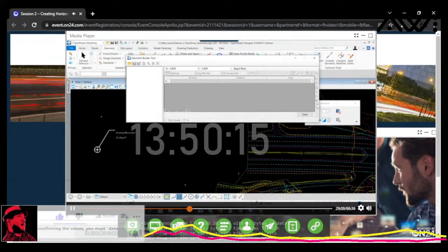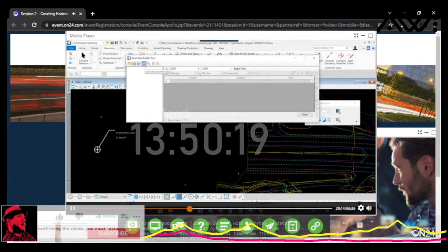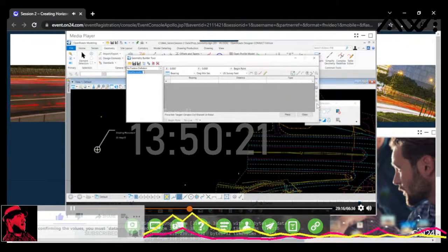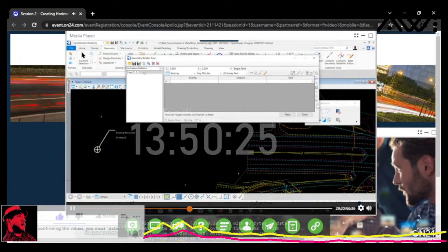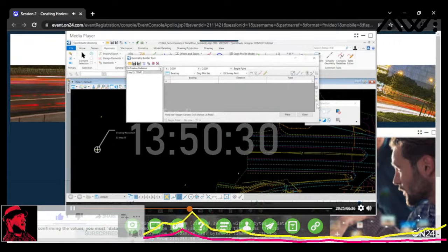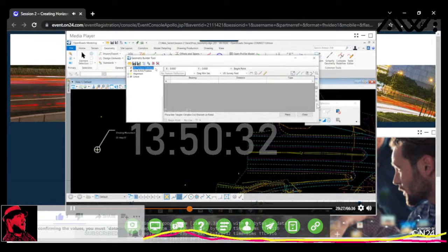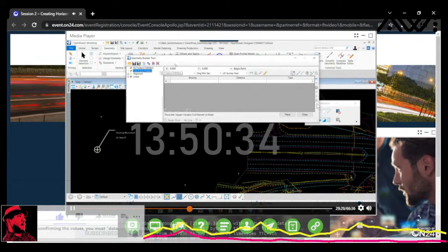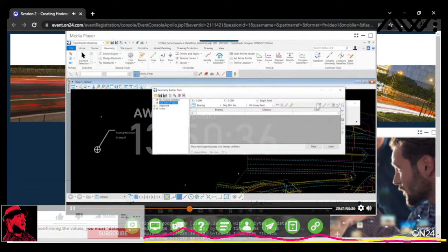Okay. Now to begin, we're going to create sort of an empty container. So this will be our geometry name, and we'll just make that temp. I can select the feature definition. I could pick a different feature definition. In this case, I'm going to use the active feature definition since I've already set it to be geometry temp. Okay.